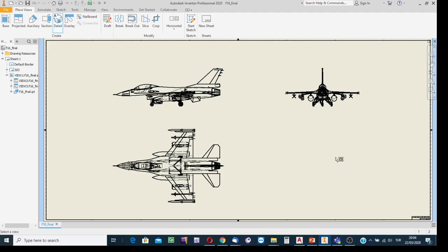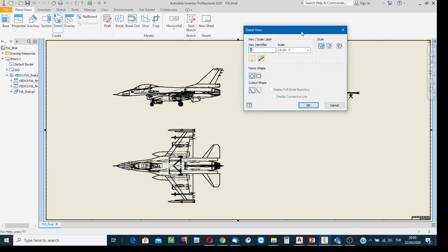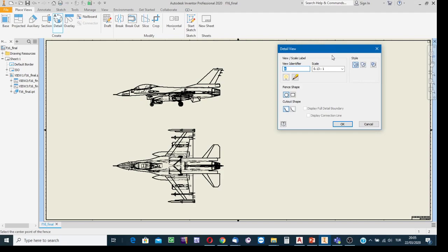In this example, say that it is on the front view. A part on the front view is to be shown under a greater scale factor. So move the cursor to the vicinity of this view and then with a click indicate. After indicating the view where the region is defined, select the scale factor in the dialog box for having a zoom in. I'm going to create the selected part under scale 1 to 1 in this example.